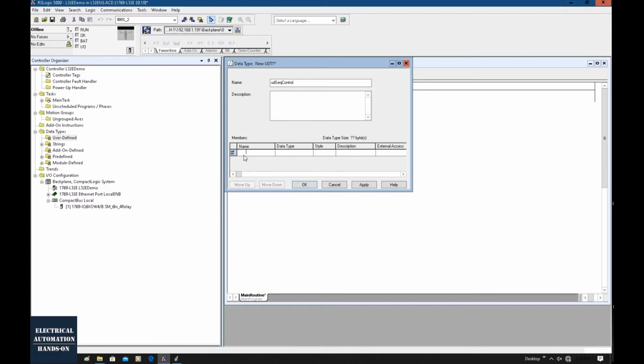First one is an integer number that represents the different sequence step. Next, sequence conditions. Those conditions are Bool signals, and they will be used to control moving to the next step. They are a Bool array, so I will name it Bool 100. Those are the sequence conditions.